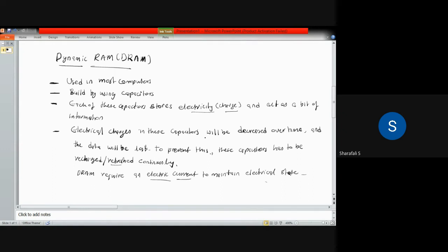That time we have to calculate, that is the hold time of that particular capacitor, and within that time you have to refresh or recharge that capacitor. According to that, we have some external circuits with the counter, and that is done automatically.